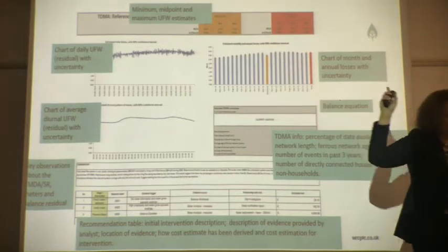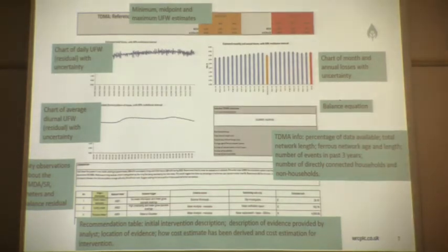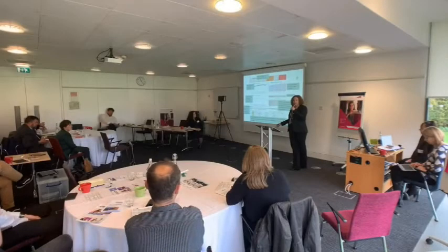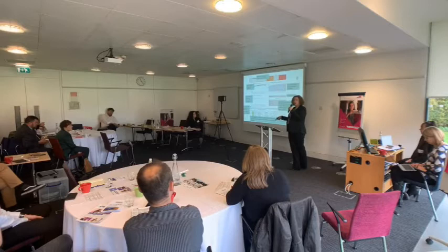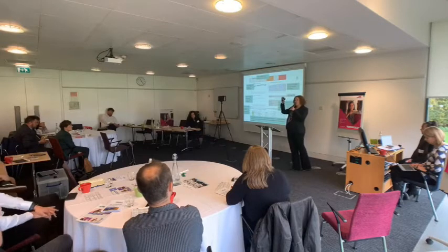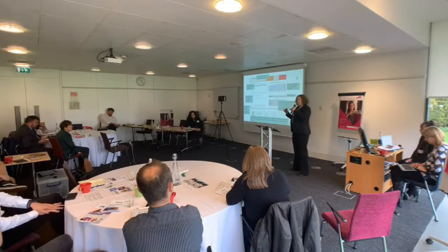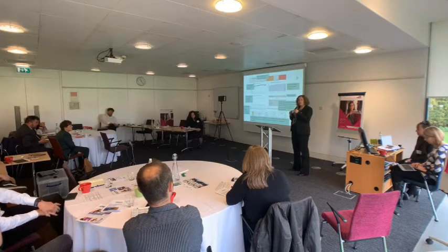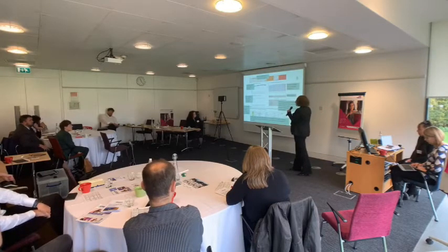If that uncertainty band is sitting above the 0 point comfortably, and there's no major metering issue like one of the meters not working, then you've probably got some sort of losses in the area, and that might be a loss going to a customer that you don't know about, or it could be a leak. And that's the importance of the uncertainty band. If your uncertainty band is crossing 0, then you might just want to get a better grip on understanding your meters to be able to work out whether or not it's worth spending any further time there.